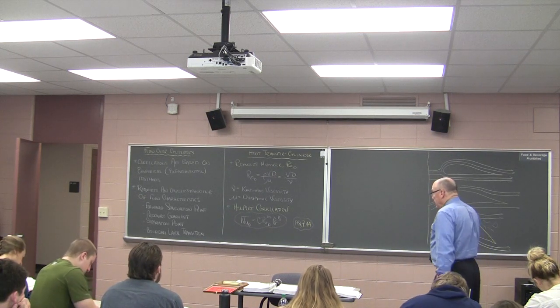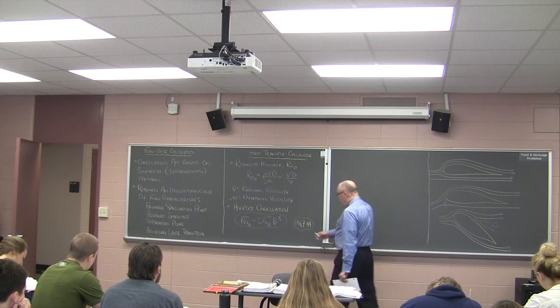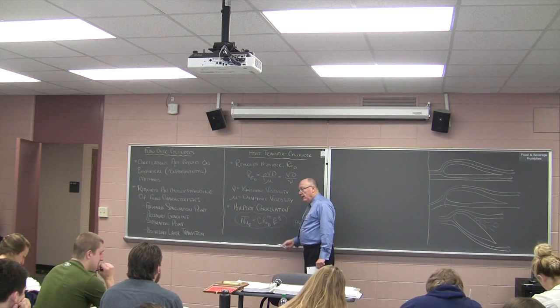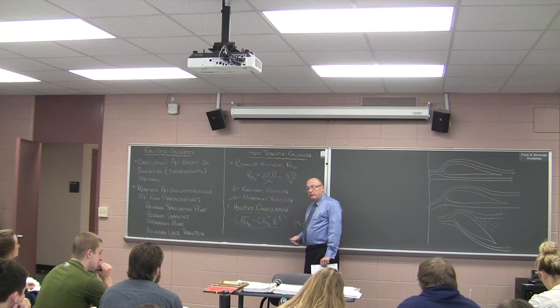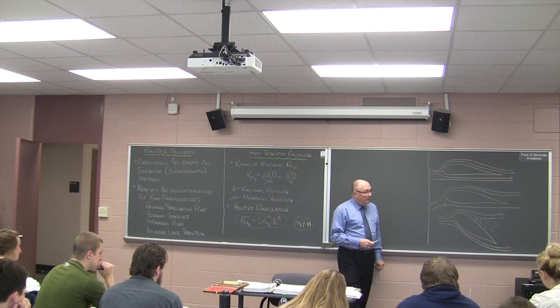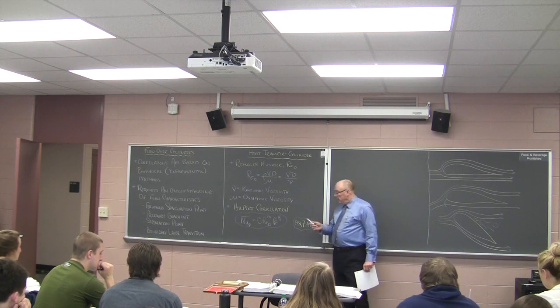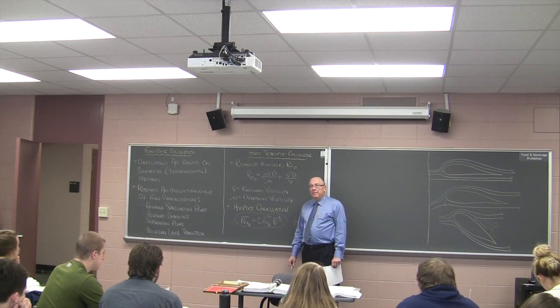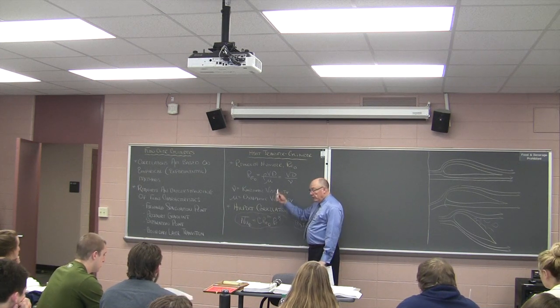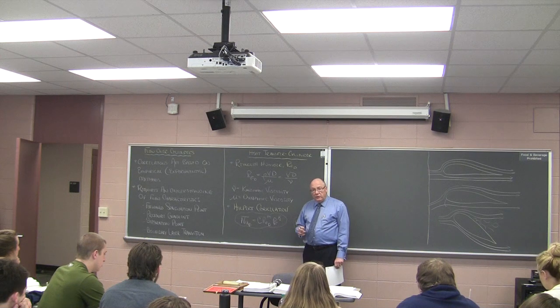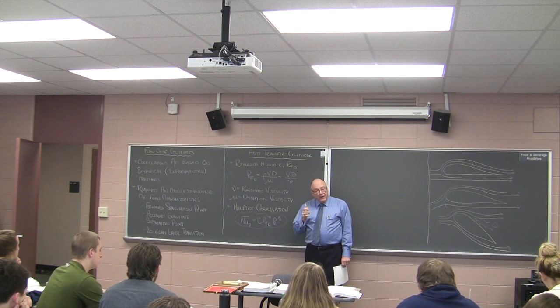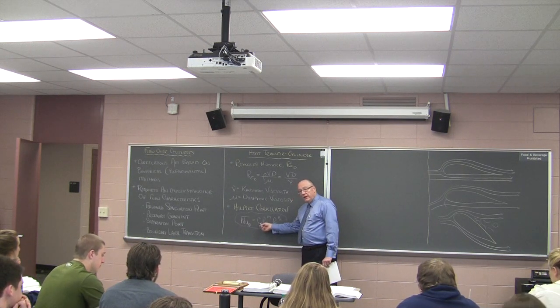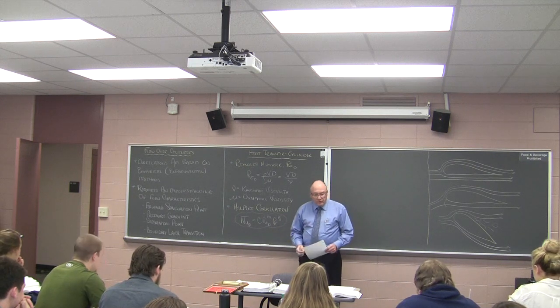Okay? Now, you may ask yourself, we already know how to calculate the Prandtl number. We know the Prandtl number, of course, is a relationship between nu and alpha. We also know how to calculate the Reynolds number. Where, you say, do you find the values of this constant C and this coefficient m?